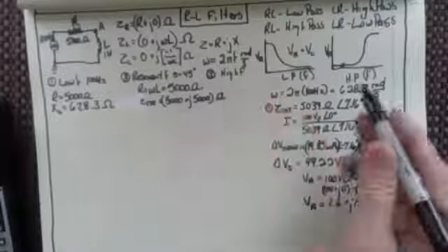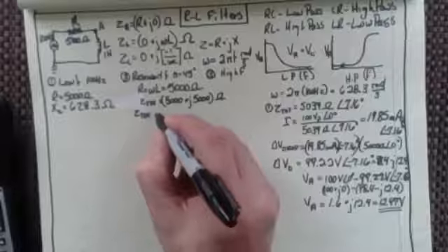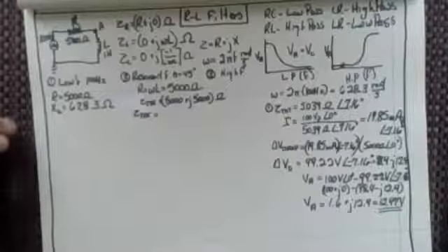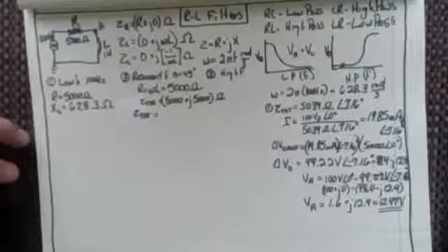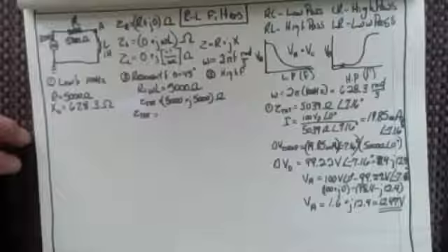I'll put the ohms on the outside. So if I wanted to find the total, and I think everybody can see that, I square 5,000, I square 5,000, I add the two of them together, and I take the square root of that. Oops, screwed that one up.